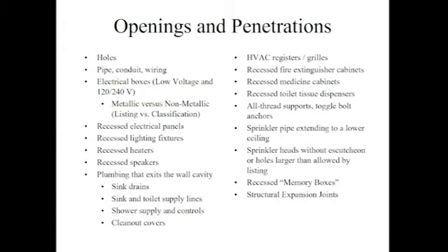You can still get rated light fixtures. They tend to be just much more expensive, and they have to be installed exactly per their listing, which can get very time consuming and expensive. Recessed heaters, recessed speakers. Heaters, you don't see heaters too often as an issue, until it's like a heat lamp or something like that, and there aren't too many rated heat lamps, not that I've seen, that can be recessed. There's plenty of them that are surface mounted. And then speakers. Boy, that's a big one.